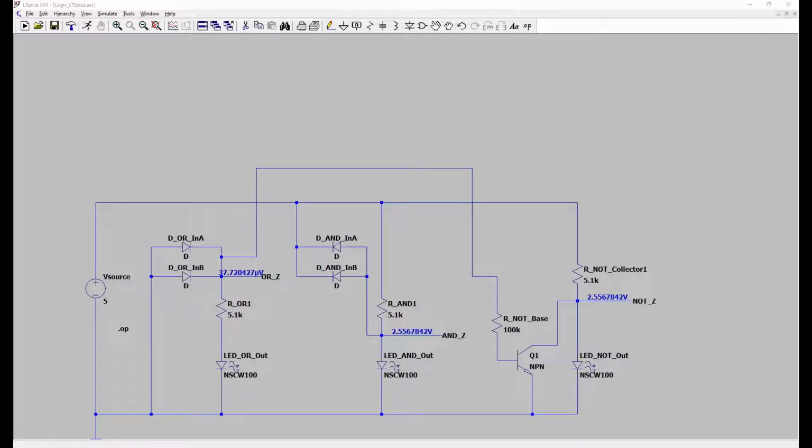Something that is maybe not possible in Tinkercad, but is possible in LTspice if we change the inputs and the simulation function, is to watch the dynamic response of the output to changing inputs. We can really only watch the voltage. We can't watch the LEDs light up, and there's no buttons to press, but we can certainly watch the output voltage relative to the input voltages.